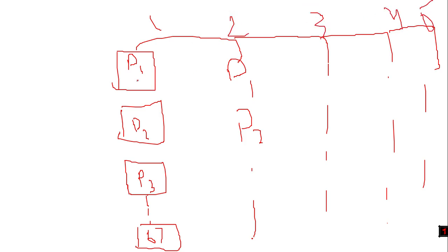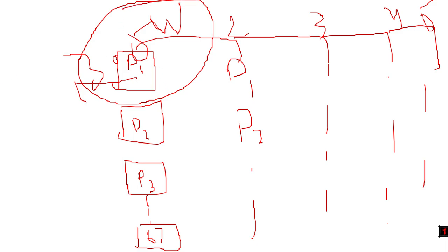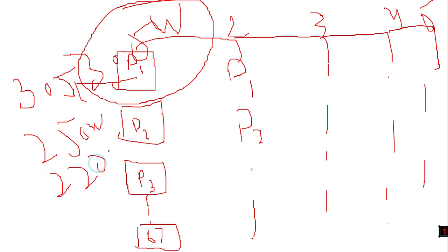So these are the 5 strings that are connected, and each panel is 305 watt, producing its maximum power. As we also know, in real life the solar panel does not produce its maximum power all the time. Like it is mentioned 305, so it will approximately produce 250 watt in actual, or 220 watt actual.